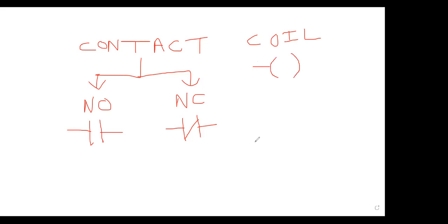Now you see another thing. Simplify this. In your program, for input, use contact. This is basic discussion. For input, you use NO or NC, like switches and sensors. If you have to represent a switch in your program, use its NO or NC. To represent the output, you use coil.